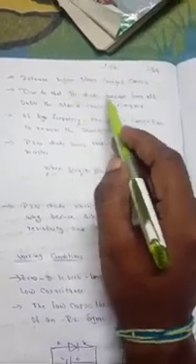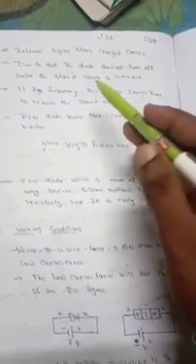Due to that, the diode does not turn off until the stored charge carriers are removed. At high frequency ranges, there is not enough time to remove the stored energy that the intrinsic material has.